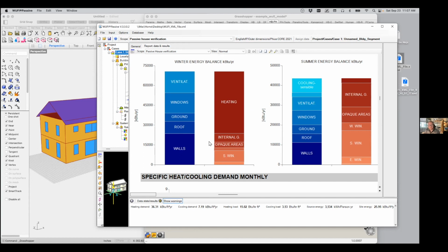Maybe we would fill the building up with thousands and thousands and thousands of cats. Each cat would emit about 50 watts of heating energy, and that would help to heat our building. That would offset some of the losses. It's probably not a super efficient or effective way of reducing the heating demand in the building. The other method, probably the more effective method, would be to focus on reducing the losses and holding the gains constant. So we really only have two methods. We can work on reducing the losses, or we can work on increasing the gains.